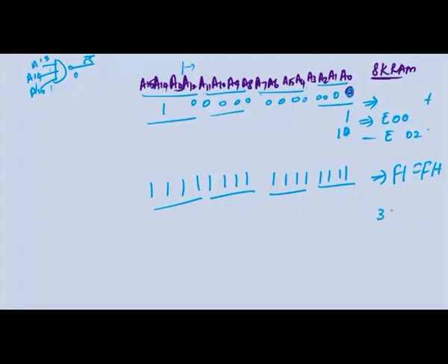In the same way, let us find it for the 32 kilobyte ROM. For that, how many address lines have we used? 15 address lines are required. So A0 to A14 we are using for the address, and only A15 is used for the chip select signal, which I have connected via the inverter. So this signal will be 1, and the remaining lines are used for the memory.